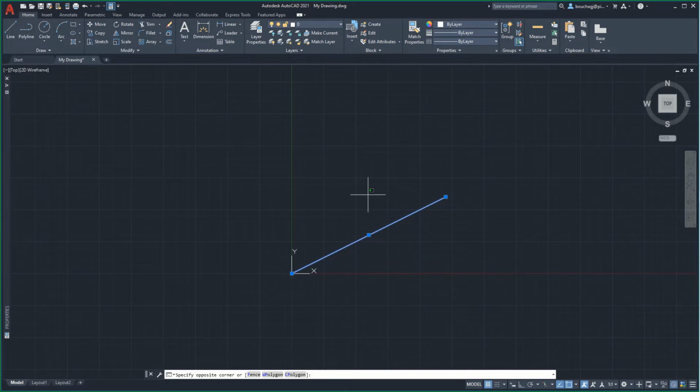With this object selected, Shift right-clicking expands the right-click contextual menu, which now contains object snap icons along with some other commands. Selecting any of these icons will instruct the software to temporarily see and recognize that specific OSNAP type only.